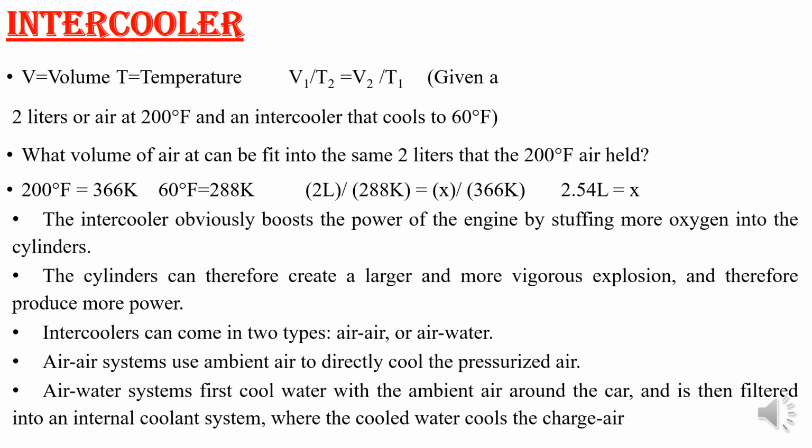So in this way we can cool your pressurized air. Then we have one more concept, that is turbocharger lag. I won't tell much about that one, so you just go through the notes. Turbocharger lag is a phenomenon encountered in a turbocharged IC engine whereby an operator experiences a short delay of full engine response after pressing the accelerator pedal.